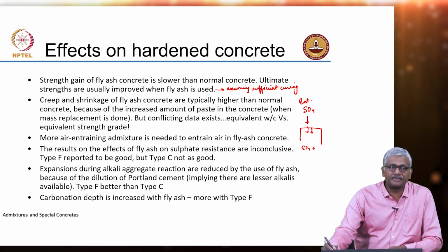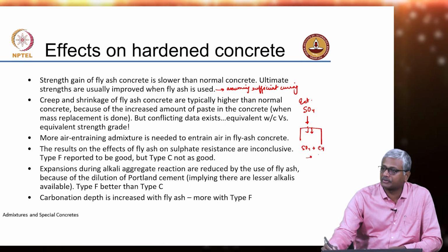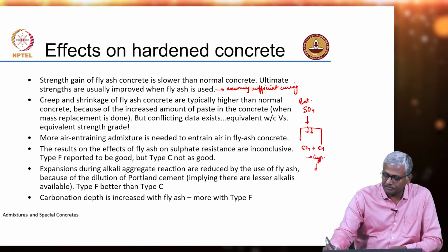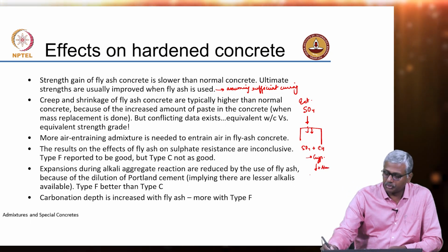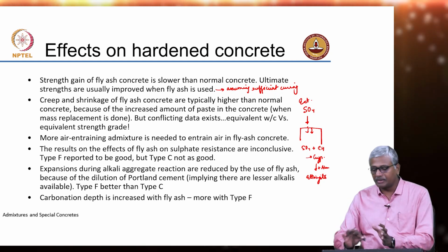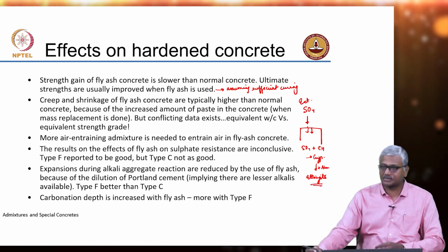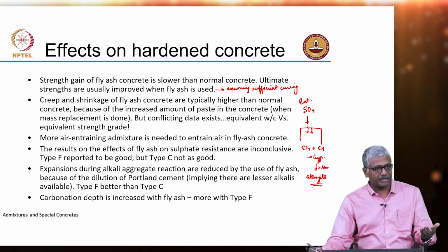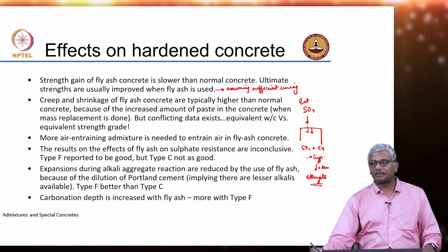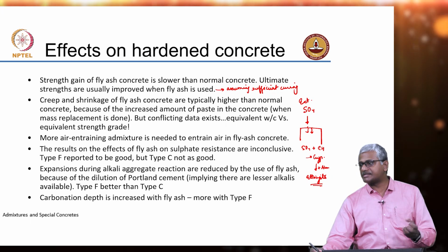The first product which is highly soluble in cement hydration products is calcium hydroxide. So, when sulfates react with calcium hydroxide, they should produce calcium sulfate or gypsum. And this gypsum, if there is aluminates present, should form ettringite. So, in a conventional sulfate attack, the formation of ettringite in hardened concrete, mind you, because this is not happening in fresh concrete. This is happening when concrete is already hard, sulfates are penetrating from external sources, slowly converting your hydration products to ettringite. Why is that a problem? Because ettringite causes expansion, and expansion in a hardened concrete system will lead to cracking.